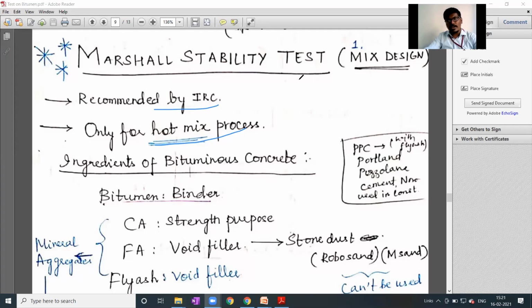There is more research going on in that, because more heating of the bitumen pollutes the environment, and more bitumen means we need fractional distillation of petroleum crude, which we need to import in our country. Because of the rise in petrol prices, they are trying to go with cold mix. Nowadays the most researched topics in transportation materials are stabilization and warm mix asphalt. Moving to the procedure.